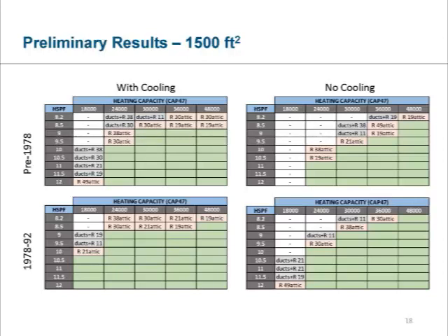If they had upgraded their windows, for example, we went with worst-case assumptions with each vintage type. At the end of the day, it might be slightly oversized and something we might have to live with. Oversizing for heat pumps is a positive thing. It might cost a little bit more, but your electric resistance won't come on as much. It's the opposite of what you think it would be.